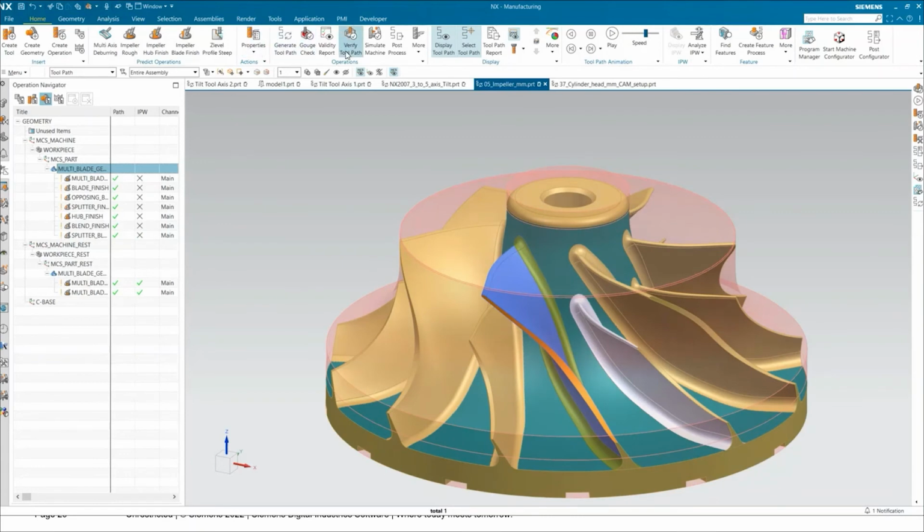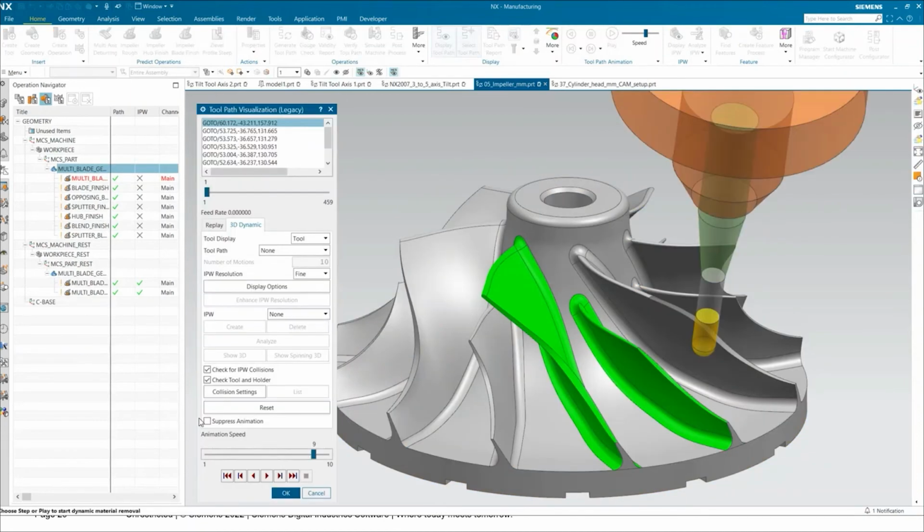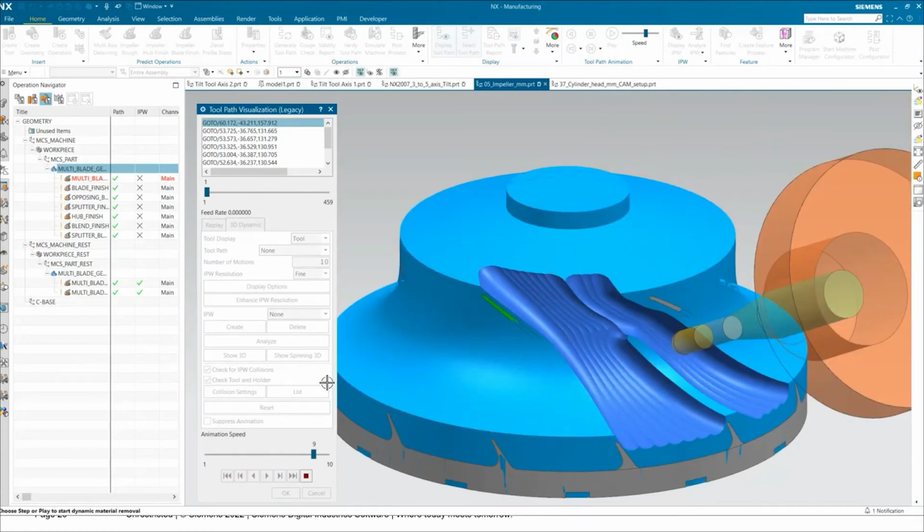So if I actually just ran all that, now what I typically do is I create this roughing, then I do an instance of those 5 times around. So then I'm doing the roughing of the whole thing. Then I will come back and start doing my finishing operations. But you can do it just like this and run it if you wanted. It'll basically do all the roughing, and I've got it turned up so it goes fairly quick.